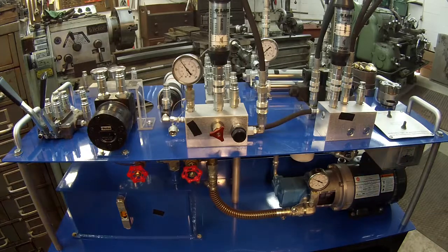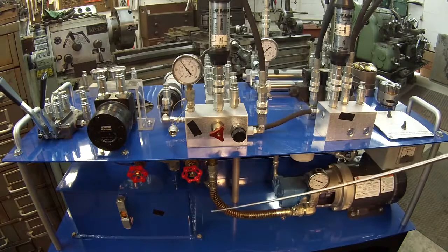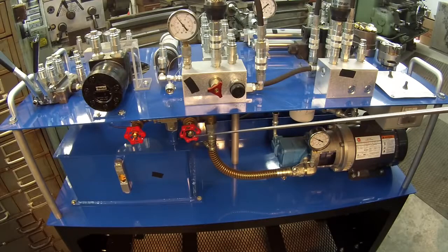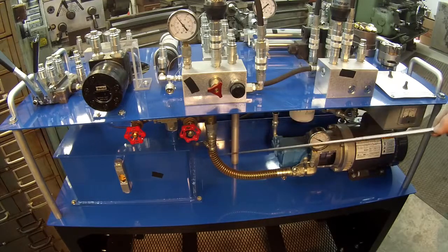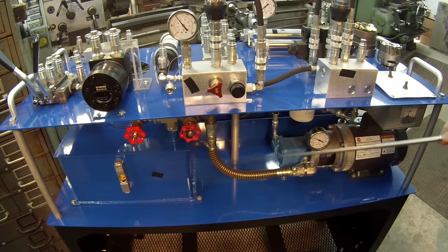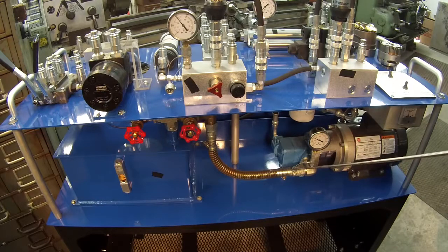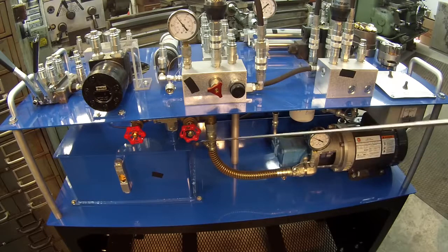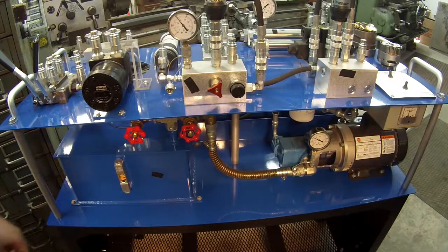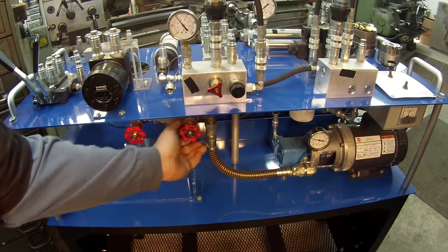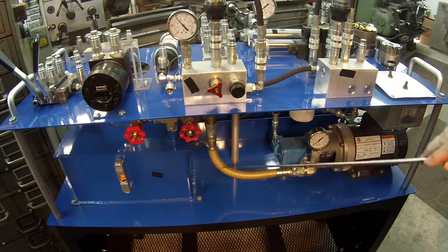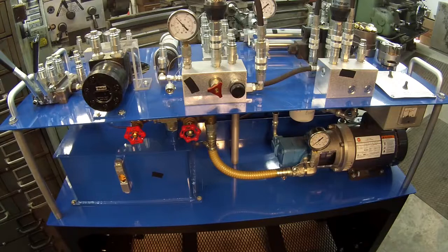What he's going to do first of all is start shutting this valve off a little at a time, and what you're going to see is little vapor cavities start forming in this hose right here. And what I'm doing is starving the fluid into this pump, and the oil actually starts boiling. That's those little vapor cavities you're going to see right here. So I'm going to get Adam, if he doesn't mind, to shut that off. Alright, you hear that? See those vapor cavities right there? That's what cavitation sounds like.